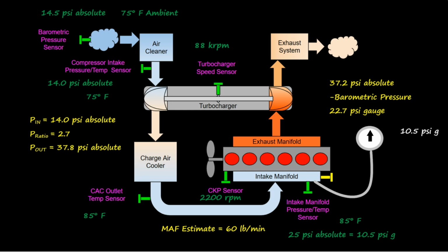So in this case, the actual exhaust manifold temperature is going to be elevated due to the reduced air to fuel ratio. So we may have a DTC for that and a derate. So in this case, if the service tool has a data point for showing the estimated manifold absolute pressure, we could compare that to that measured MAP, and that's going to help us diagnose this exhaust manifold temperature diagnostic trouble code.